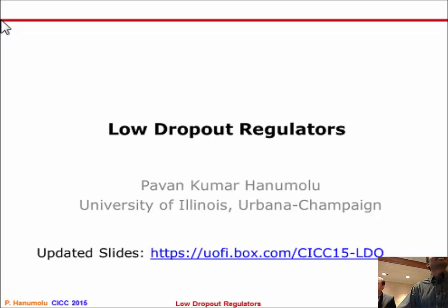We have a couple of questions. Thank you for your introduction about LDO design. I have one question about your compensation design. For the cascode compensation method, I see you need an additional current source to generate a compensation circuit. But will this reduce the current efficiency of the regulator? No.